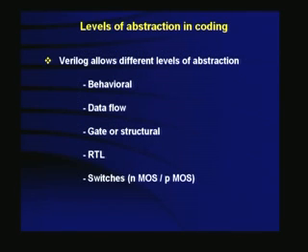Verilog allows different levels. I can describe the behavior of the circuit. I can give the data flow of the circuit, or I can give a gate or structural level description. I can give an RTL. RTL means register transfer language. It is register transfer. Or it can also be switches, NMOS, PMOS type of thing. You can go to that level.